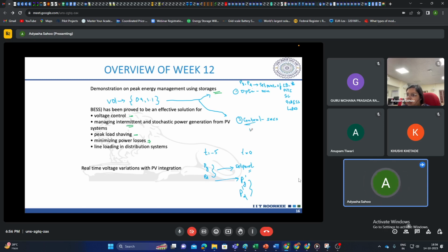So they act in near real time basically. They will sense the voltages in real time, and depending upon the control algorithm, basically the QV control algorithm that we have, like droop-based controllers, they will change these set points to set point dash to manage this PG dash and PD dash changes so that your voltage is within the maximum and minimum limit.